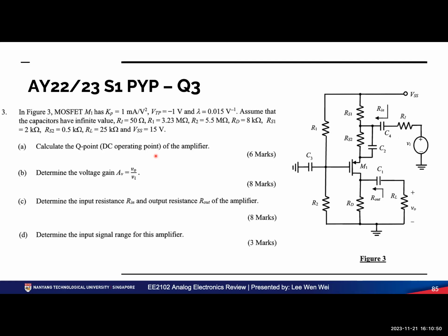Okay, so for this, right? Use this one. We need to open the capacitor. What happens is we short the independent sources to ground. Here is ready to ground. Here this is shorted. DC is open. This is open, and then here is open. So open means we need to include R2.